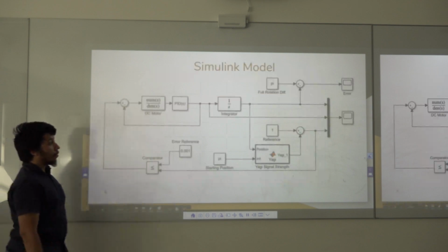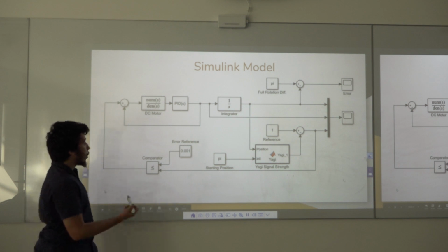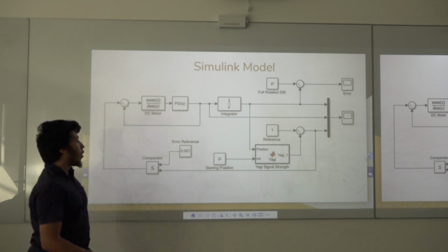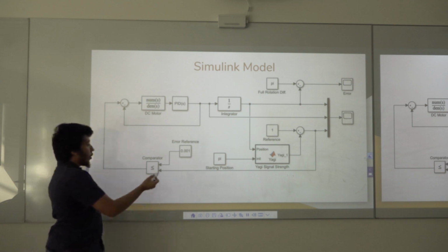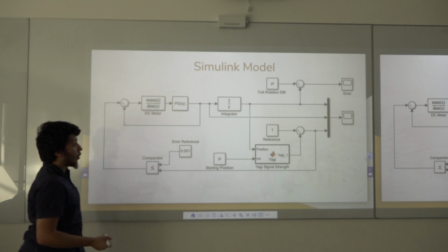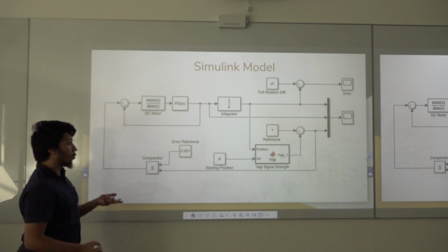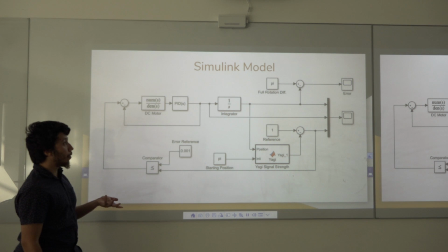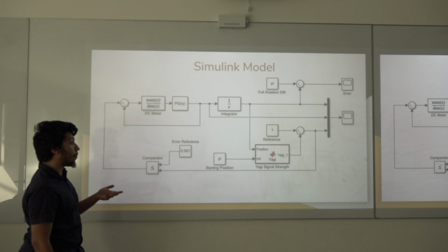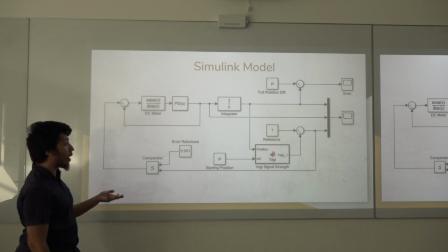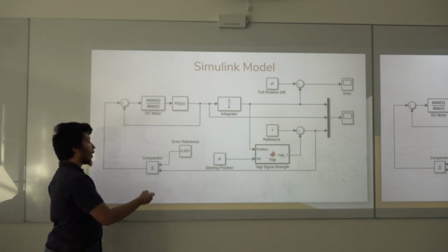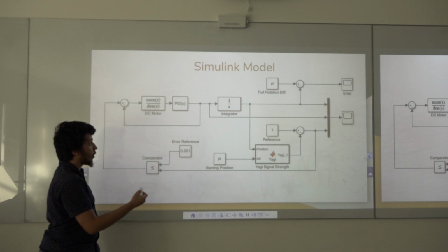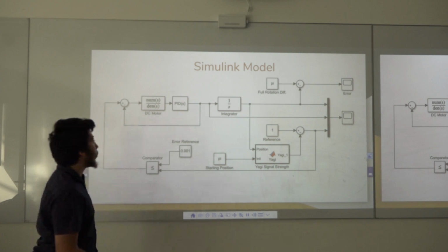In our Simulink model, we start by initializing with some values. First, we define a threshold for our comparator. The threshold is really important for the function of the system. We have to make sure that our reference signal is greater than the expected noise on our frequency. If we receive too much noise, then the behavior of the system will be very irregular at the final position and may never find the direction of our signal. So it's really important that this is at least greater than the highest noise we expect in our system.